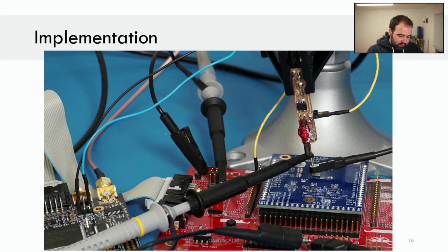To drive this, I'm actually using a ChipWhisperer here. So this just generates a glitch output. So the ChipWhisperer, as part of any of the glitch logic, can generate a pulse. In this case, I use that pulse to drive the MOSFET that then inserts the glitch here. So you can use whatever method you want to generate the pulse. It just needs some sort of logic level pulse. So the requirements around this are pretty straightforward.